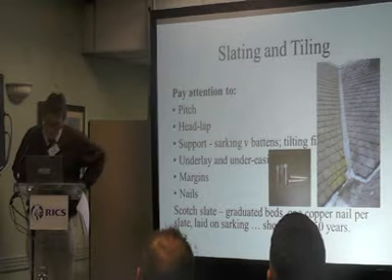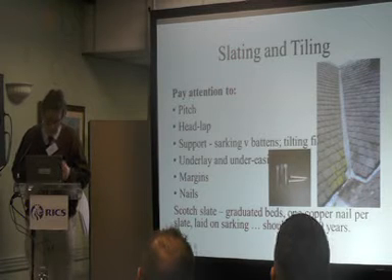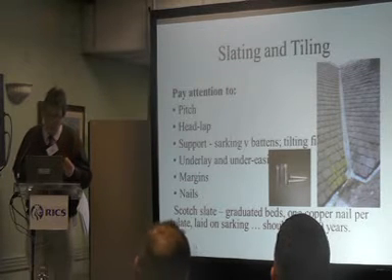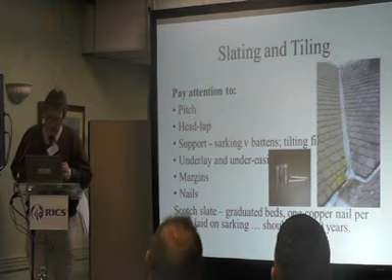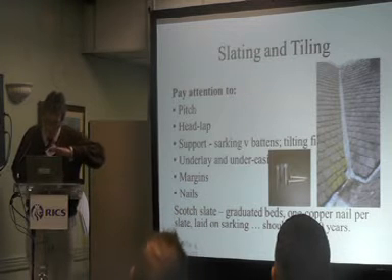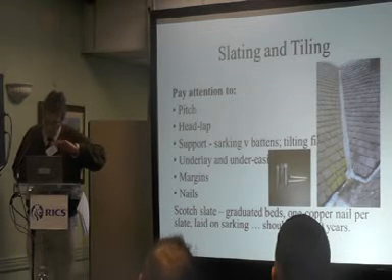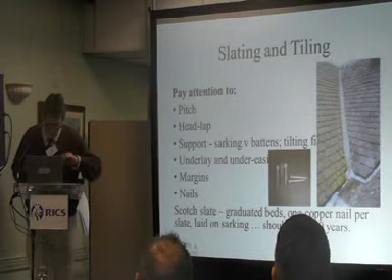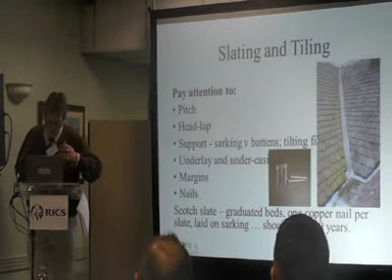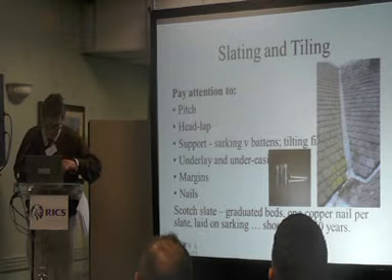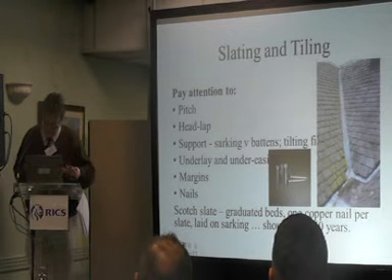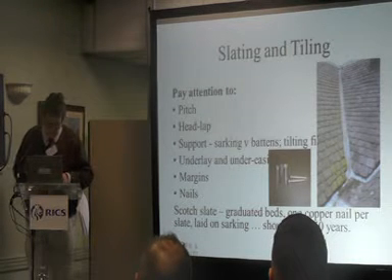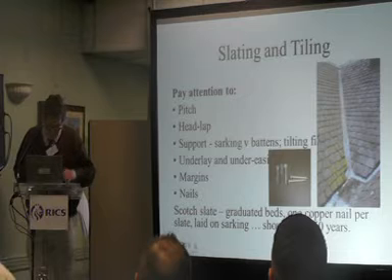One of the troubles with a galvanized nail, especially if your slate is quite rough, is that over the years it will rub and chafe on the collar of the nail. It'll take the galvanizing off, and the nail head will pop off, and you've lost it. Copper is a softer metal, but it doesn't depend on a galvanizing coat, so you're better off all round. If you can use stainless steel pins to hold the timber together as well, so much the better.